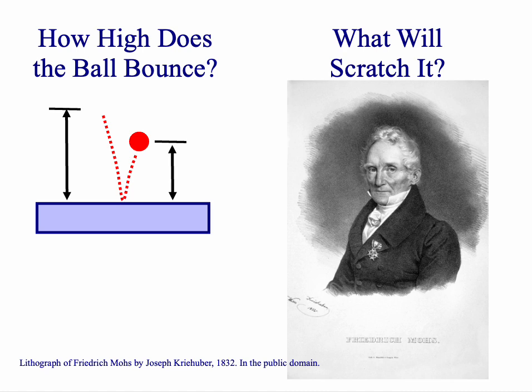In 1812, the German geologist Friedrich Mohs invented one of the first hardness scales. The way this works is you scratch the sample with a variety of different materials, ranging from talc to diamond. The hardness of the material is determined by what will scratch it. The scale is not linear, but for geology that's okay. We don't use the Mohs scale for traditional engineering materials, but it is used for some ceramics and some ingredients of ceramic composite materials, like the grit used in grinding wheels and sandpaper.